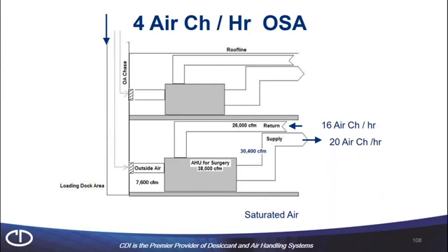This is showing an elevation view of an equipment room coming down the outside air shaft, our outside air coming into the air handler, the return air coming this way. We're blending that air. We're going to cool it down basically to the point of saturation to get that moisture to come out. And then the fan, maybe some final filters, and we're going to then discharge that very moist or potentially saturated air into this ductwork until some point at which it's going to be reheated.